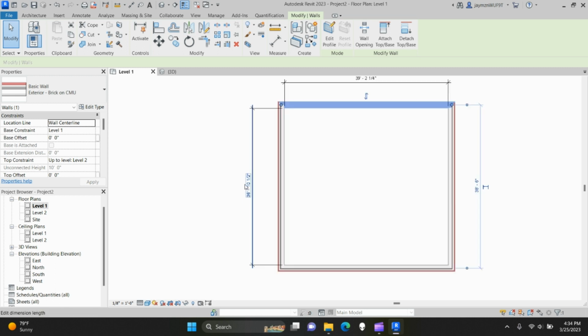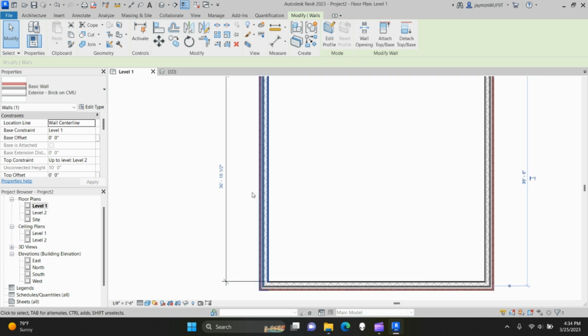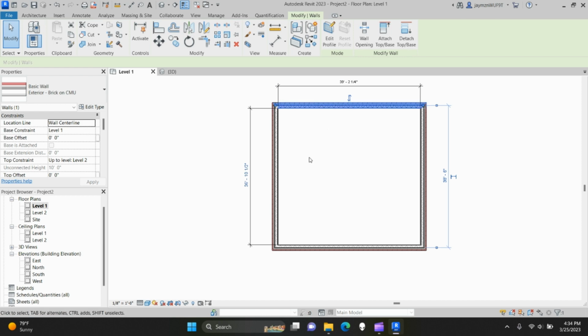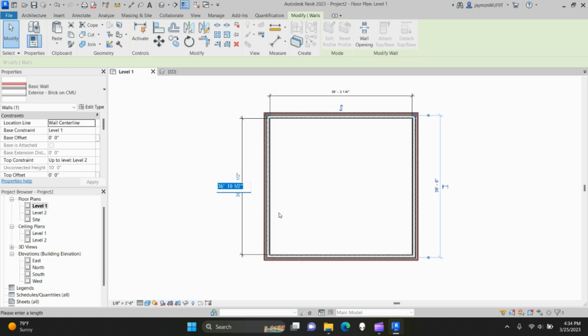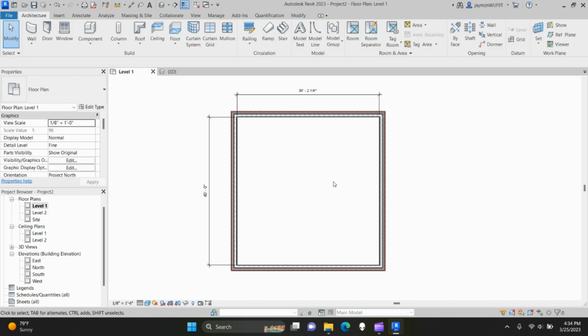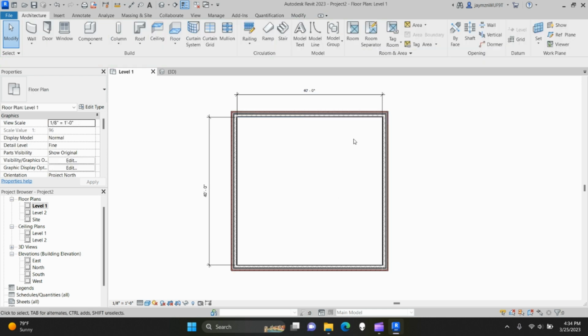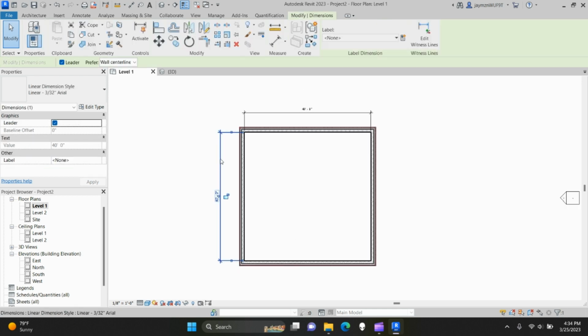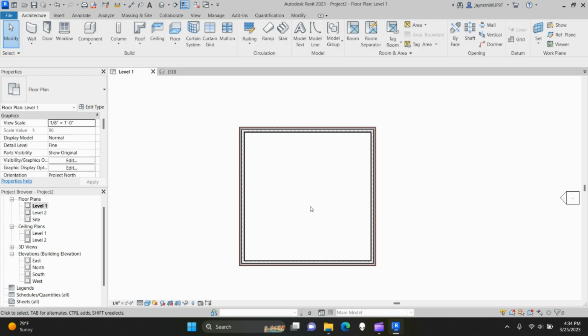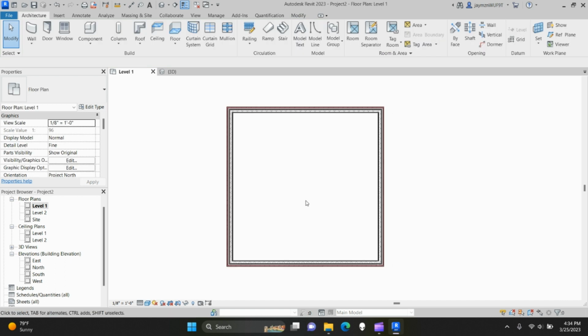So I never use that. I use my align dimension tool. I can click and drag the wall and move it. Easiest thing now that it's highlighted. Whichever wall you click is the one that's going to move. So this is going to be the wall that moves. I'm going to type 40 and enter. Do the same thing here. I want 40, enter. Now I have 40 by 40 interior. I don't want these, so I'm just going to click and delete, and they're gone. So now I have my exterior walls.